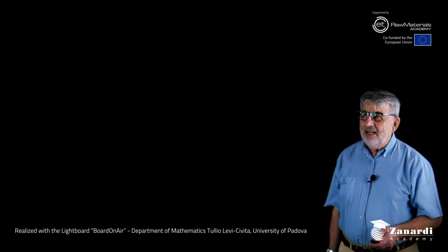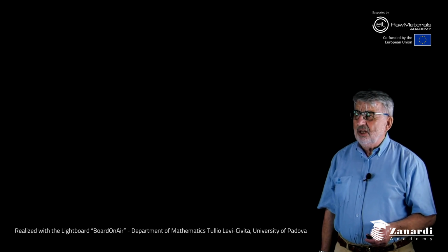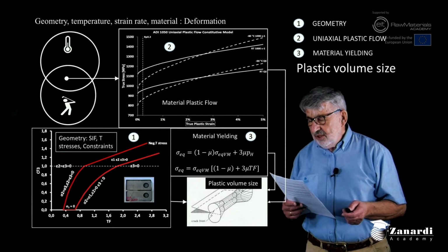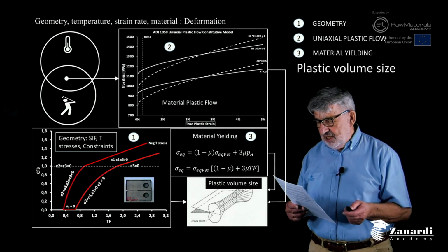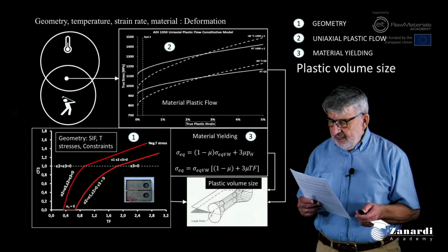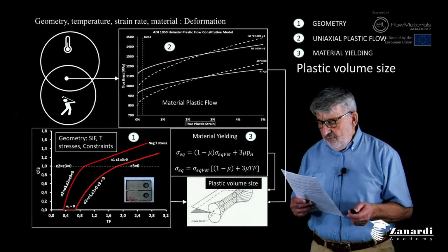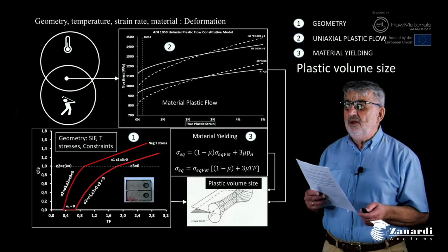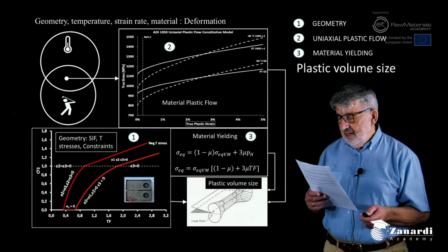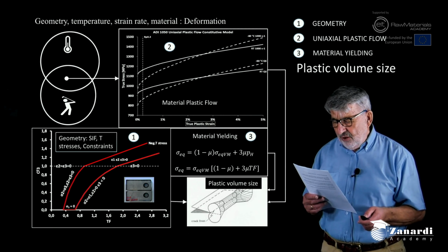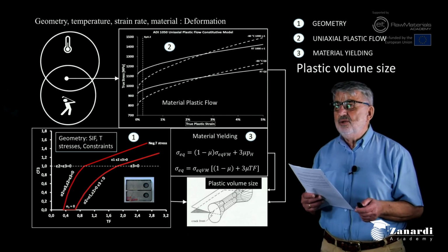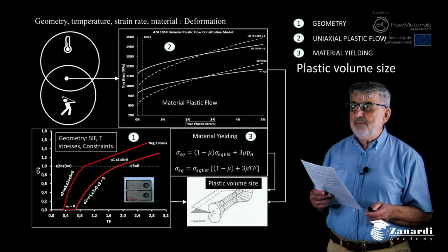Welcome to the video Key Properties: Toughness. A linear elastic finite element model calculates the state of stress beyond the crack tip for an ideal material. The state of stress is approximately identical for all ferrous materials, depending on the elastic parameters. It defines the constraints to the plastic flow development, and this with reference to a CT ASTM specimen,